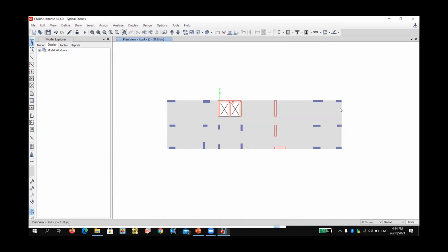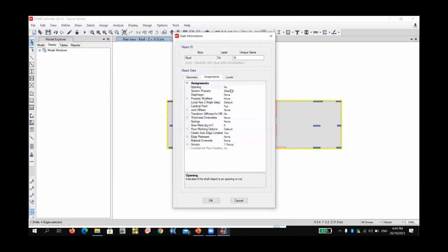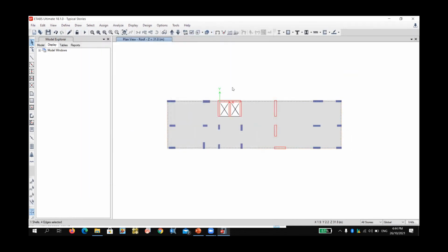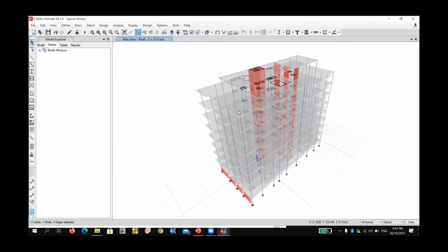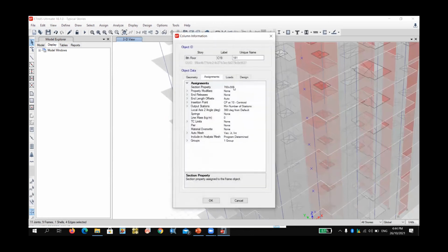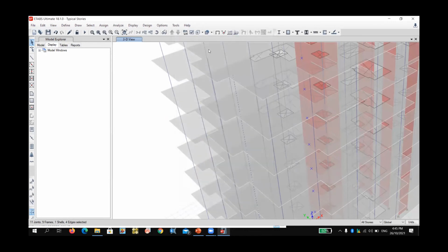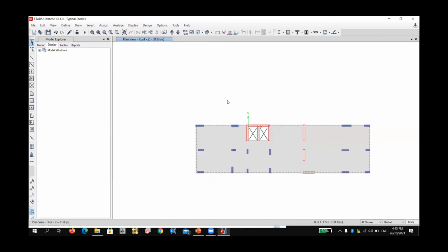We made all the model now with the columns definition, with the material, with the slab. Slab thickness is 200. Right click and see. You can see for the columns. For example, you want to see this column label. You can see the properties is 700, 300. Okay, and name C19, and view.